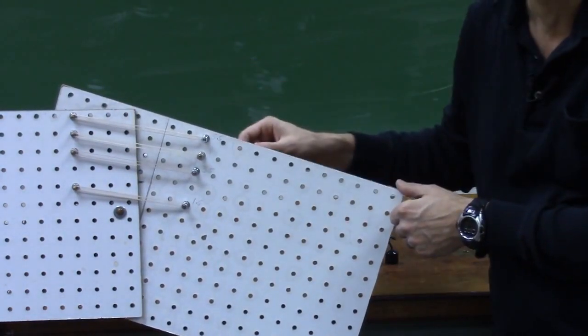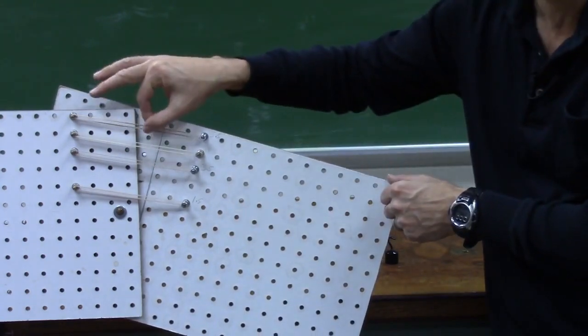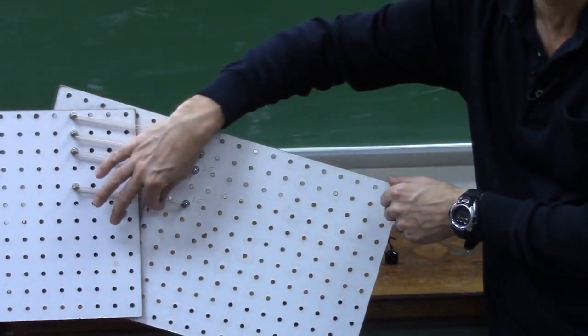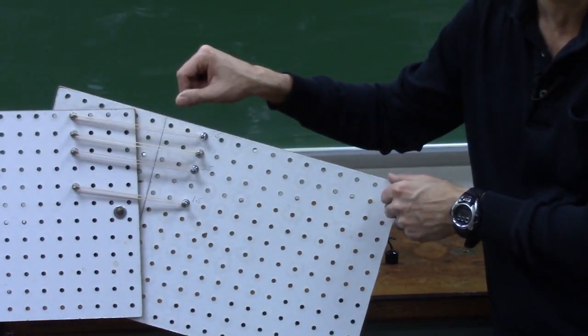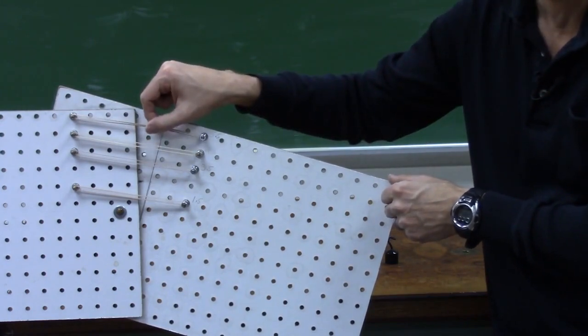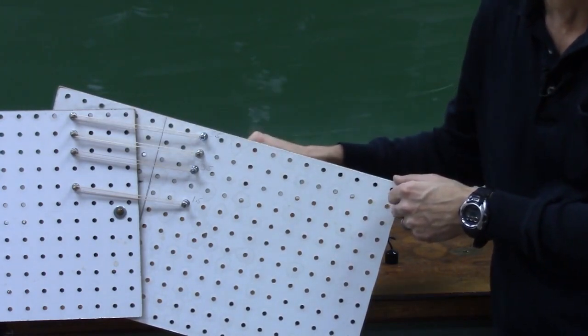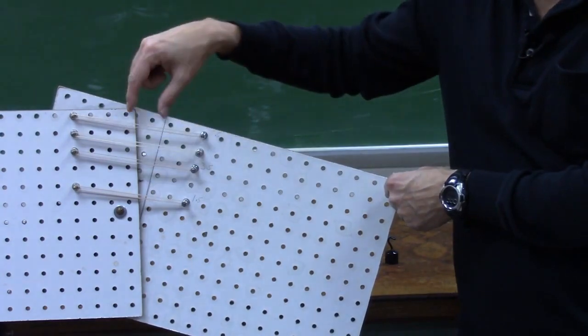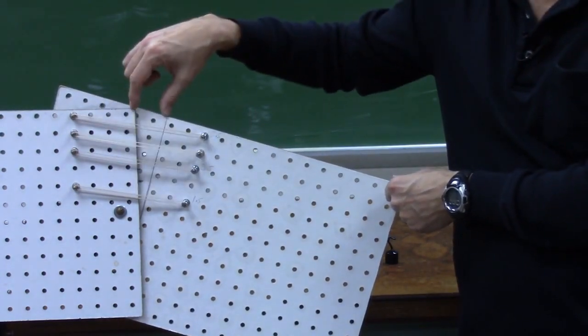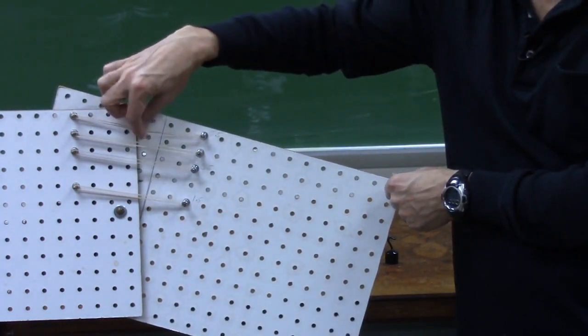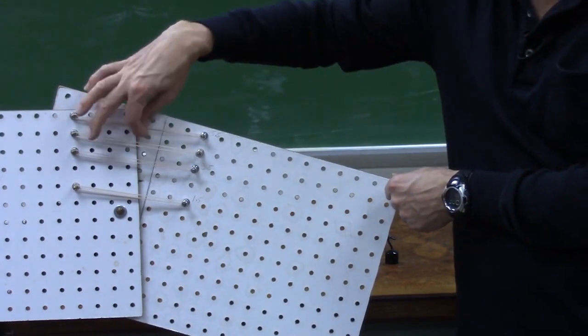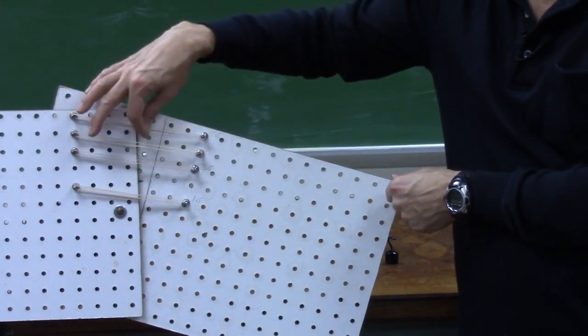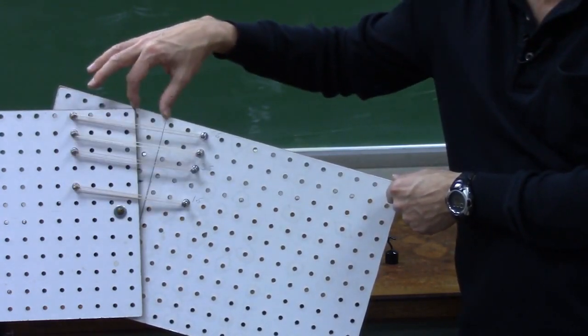So the top is in tension, the bottom is in compression, and you can imagine that this rubber band is stretched the most and this rubber band is stretched the least. And then if each rubber band were a Hooke's law spring, then the force exerted by each rubber band would be proportional to how stretched it is. So statement 1 is that this strain is proportional to how far up we are above the neutral surface. Statement 2 is that the stress is proportional to the strain. That's Hooke's law. That means that the force exerted by each little fiber is proportional to how far up that fiber is from the neutral surface.